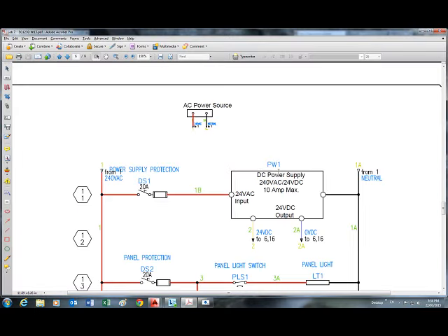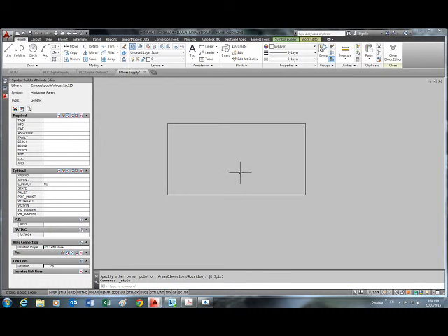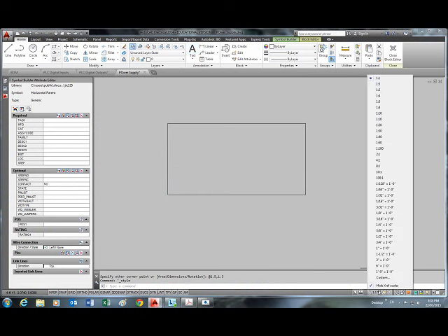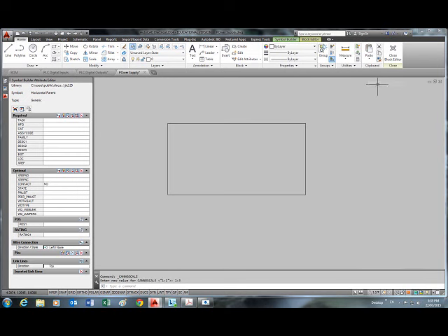start writing these labels. Okay, so notice, of course, we must set the annotation text scale to 1, 2, 3. Start, and then we'll open.